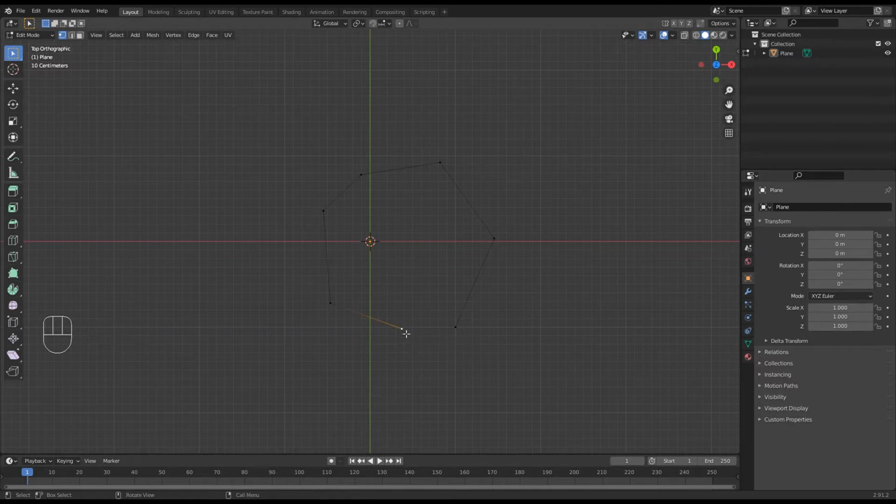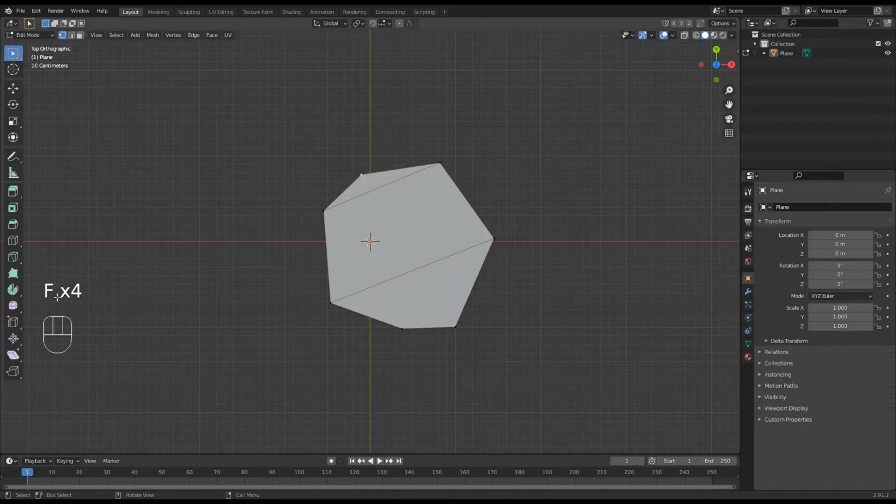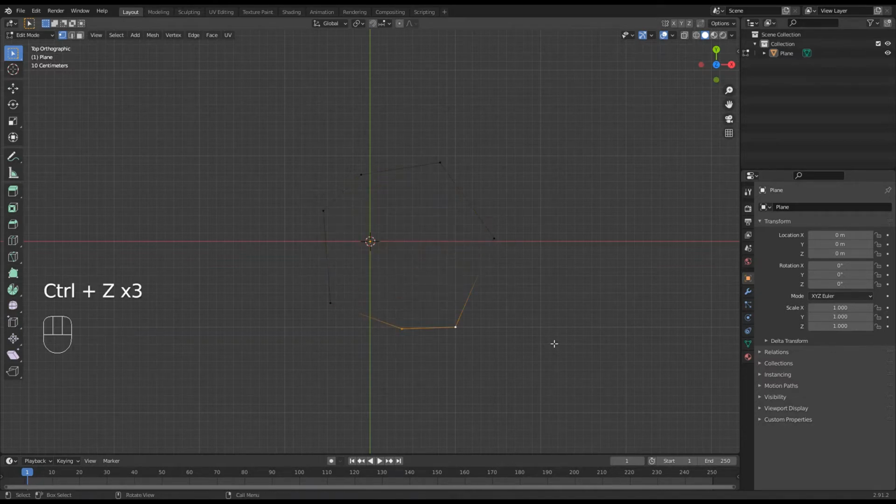So now what I need to do is join this dot to that dot. This one is already selected, so I hold down Shift for multiple selection, and then it is left click because I want to select that one, and now both of those are selected, and the key shortcut is F for fill, so we want to fill the gap here, so press F. Whoops, it was a bit more than expected. Control Z, Control Z, Control Z. All I wanted to do was bridge it. I held it down too long, so it started filling up the whole region.